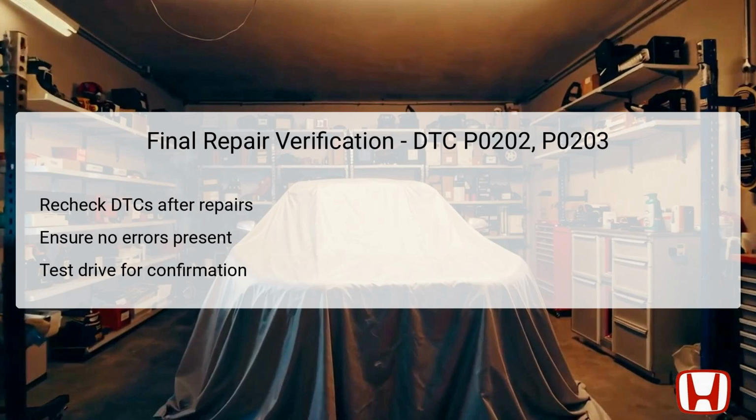Upon completing repairs related to DTCs P0202 and P0203, follow up with a final verification of the system status. This includes rechecking the DTCs using the HDS to confirm that no errors remain associated with the injector circuits.